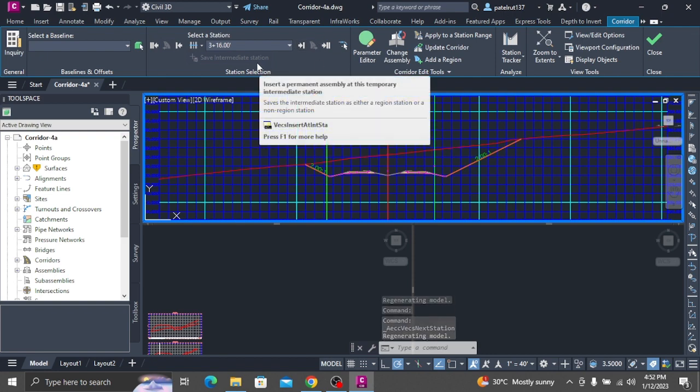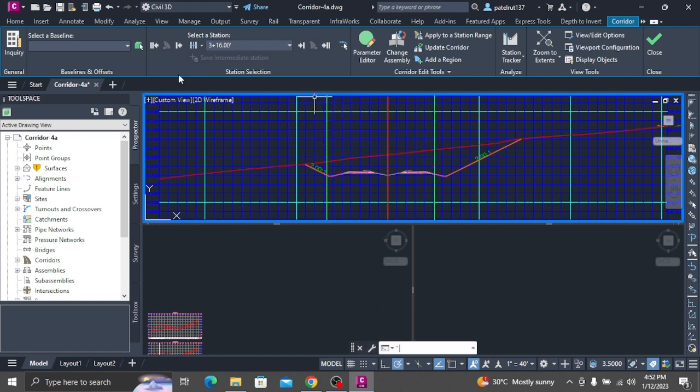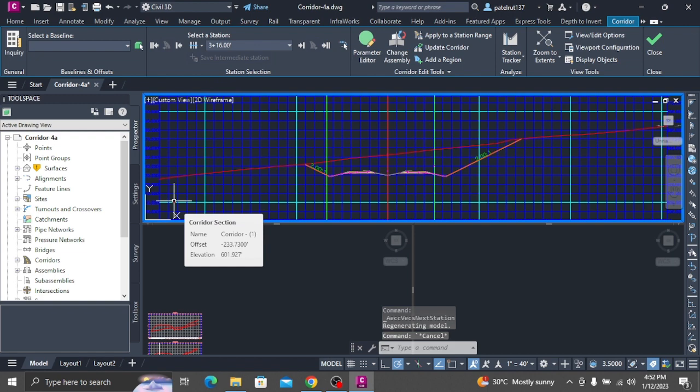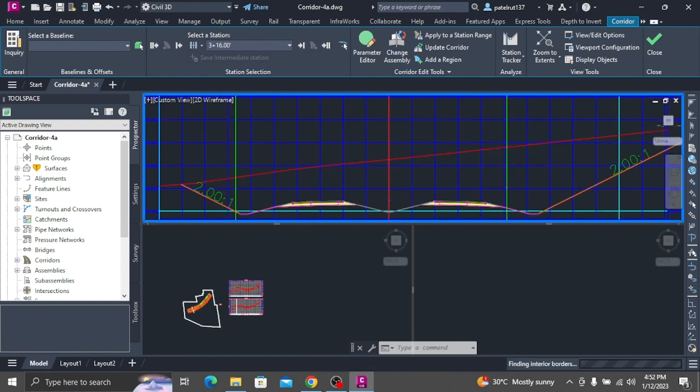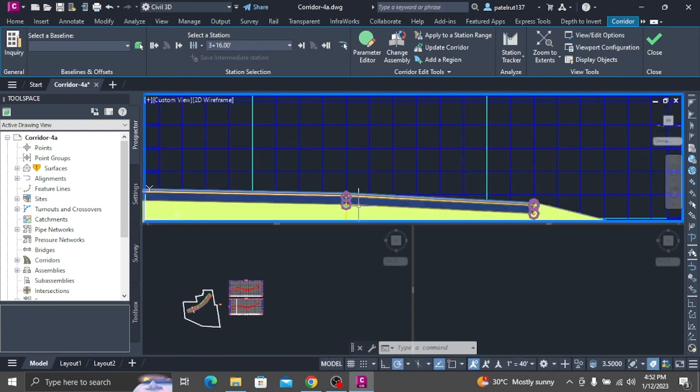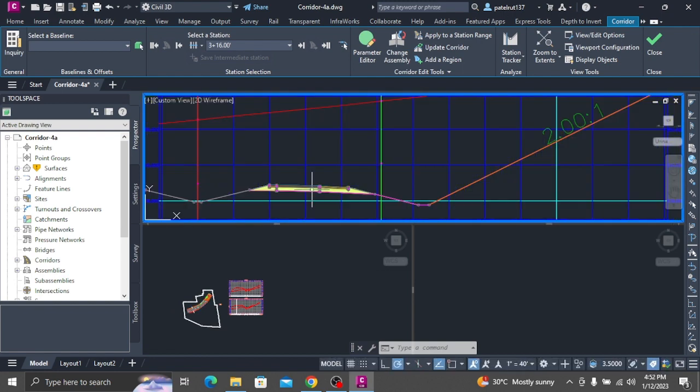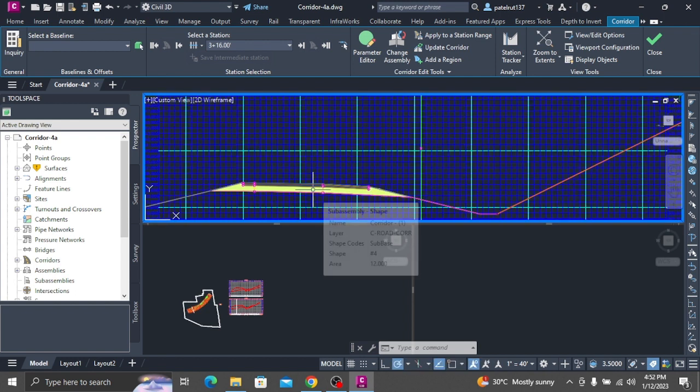In the Corridor Parameters dialog box, in the Assembly 1 tree, under Group 1, expand Lane, Right. Change the width value to 36.0000 foot. Notice that the Override checkbox is automatically selected, which indicates that the design value has been overridden at this station. Click Go to Next Station several times. Notice that for the other stations, the width value is 12.000 foot. The lane subassembly that is displayed in the section view updates in width to reflect the width at the current station.